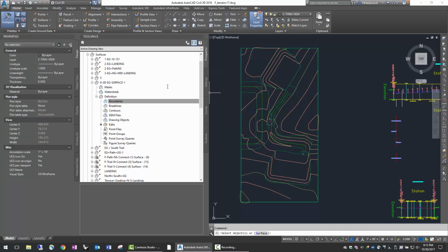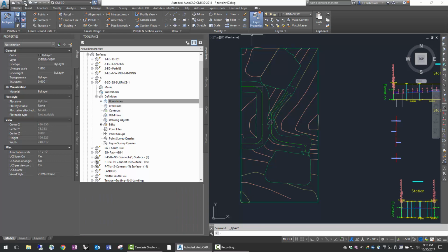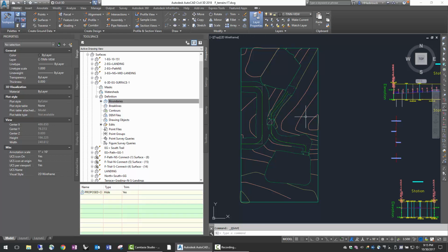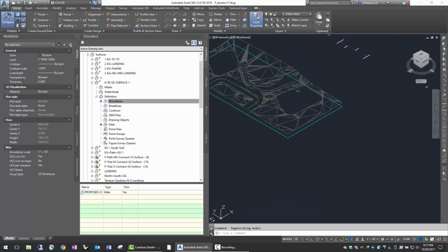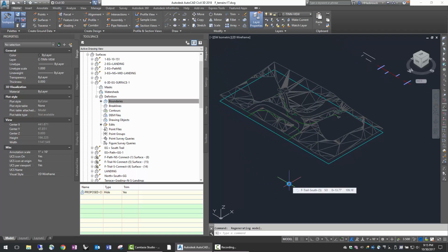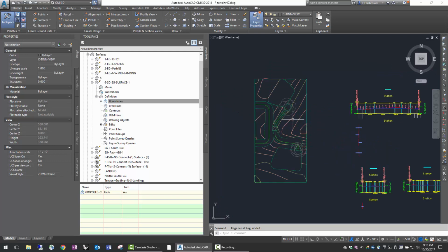I'm going to use that to clip. So good. Now I'm going to select that object, hit return, and there we go. So now we have a halfway decent surface that we know will meet our proposed surface once we bring it into Max. This was the error that I made the last time. Okay, so I tumbled it just so you can see the holes there for the grading for all the proposed business. That's just as we want it.